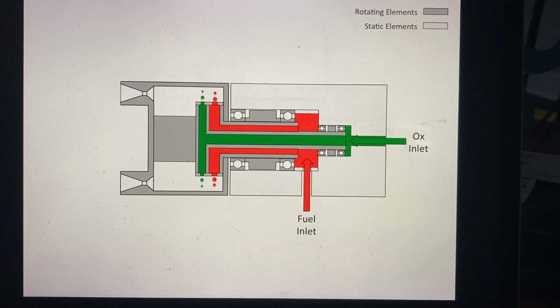During rotation, the propellants are injected at high pressure within the combustion chamber, where they atomize, vaporize, mix, and burn to produce a hot, high-pressure working fluid. This working fluid, or combustion gas, exits from the turborocket through a series of nozzles. These nozzles are at an angle relative to the axis of rotation of the system and impart a rotation to the system.